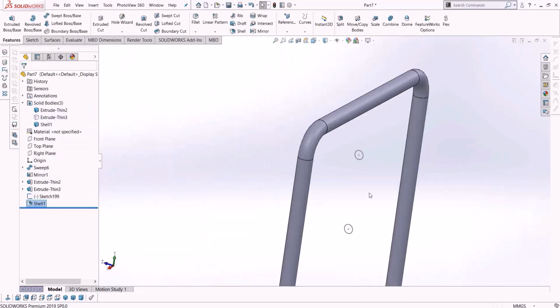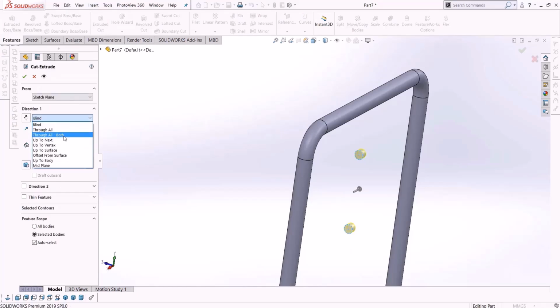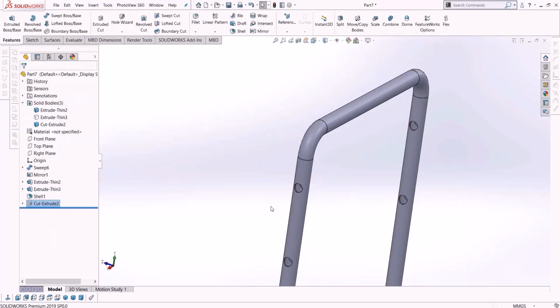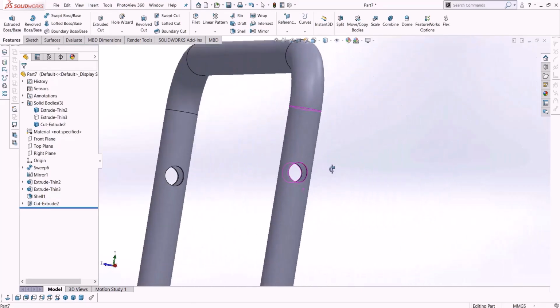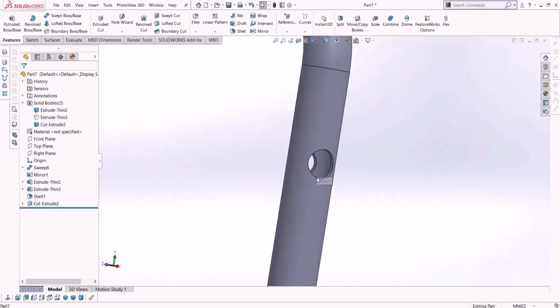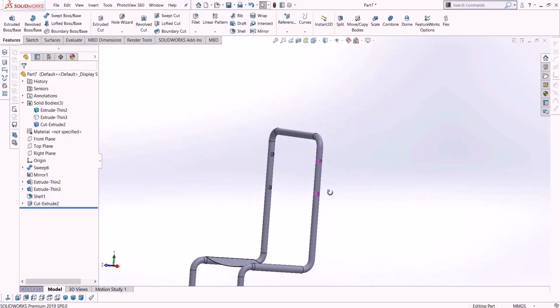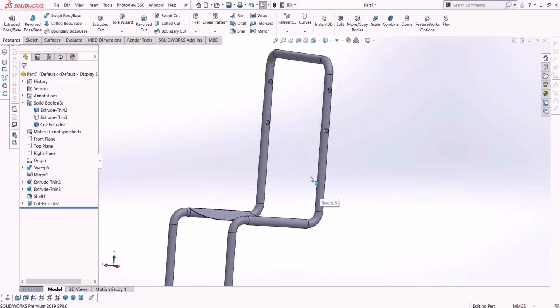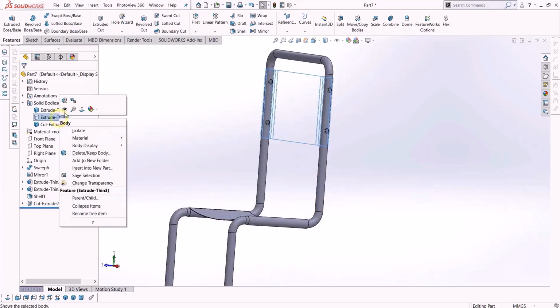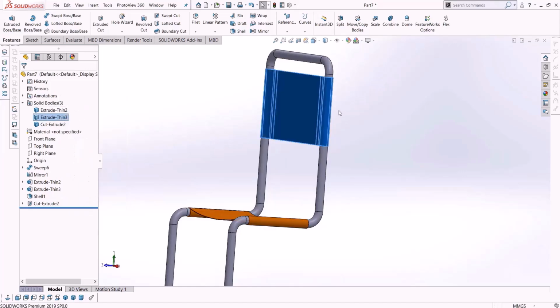Let's say 2 millimeters. Now this profile has holes created in it, meaning it has been hollowed out. Now if I come and actually extrude this sketch we have here and cut it from both sides, we can see the difference. You can see that these areas are no longer solid. We used the profile in a loose manner. We haven't done anything specific for the vase yet, but we will do it on this.